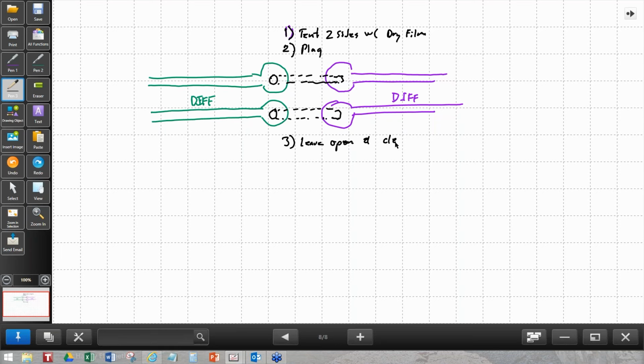As long as both sides are completely open, your cleaning process, if it's good, ought to be able to do that, as long as L over D is on the order of 8 to 1, sort of. If it was 10 to 1, it would probably work. If you try to get 25 to 1, I wouldn't trust that as a cleaning process. So those are basically your options. Are there other options? Possibly, but they get kind of strange.